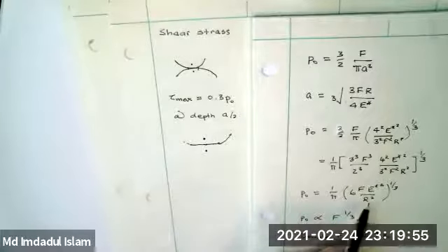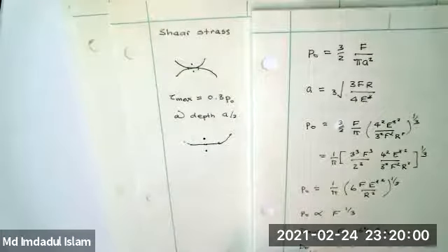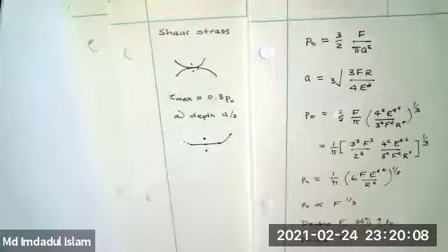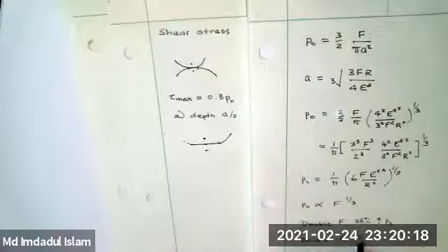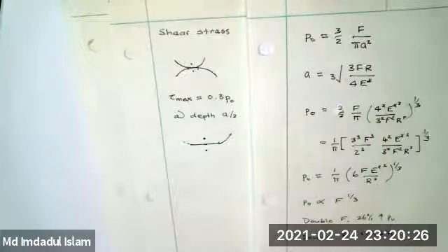On the other hand, for R squared, it's R to the 2/3. So if you double R, which is what's often used to try and mitigate these stresses, you try and increase the radius. Some of these radii are local. Then you actually get this going down by R to the 2/3, down by 37%. And in fatigue problems, dropping things by 33% or so, 37%, it can be quite significant. Okay, it can really be quite significant.